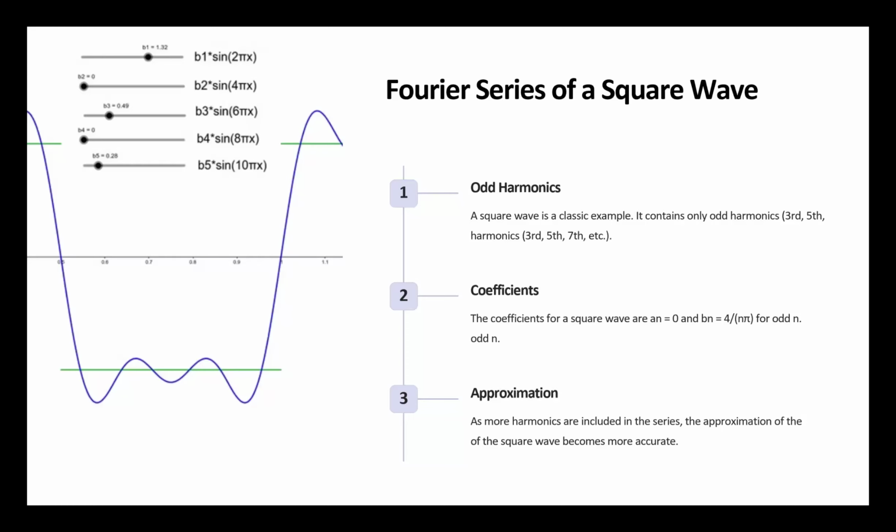Now, the coefficient: if you run a Fourier series on a PWM, you will find out that the coefficient of each of those frequencies is going to be 4 over n pi, times the VDC, which we have. Here in this equation, I consider per unit, so VDC is 1 volt.